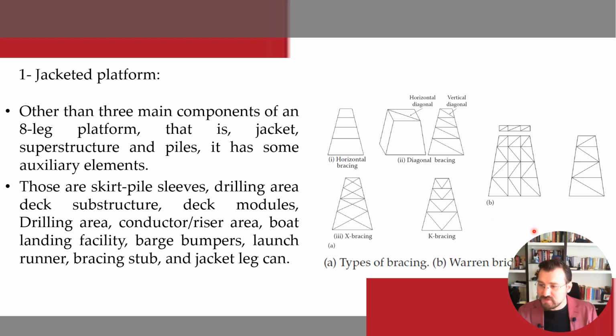all jacket. Okay, so skirt pile sleeves are used for driving skirt piles in between main piles around the periphery of the jacket leg. All right. So I'm just giving you this as general information, to make you familiar with this type of environment and the tools used in building the legs and other things of a platform. All right. So these skirt piles are used to increase the capacity of the structure in resisting the overturning moment. Actually, all right. Okay, go on.